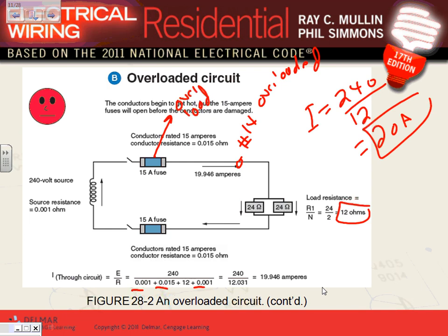That's an overload condition. What happened in an overload condition? This fuse will sit there in this situation probably for an hour, half an hour and a half, and it will open. So look at the amount of time that it takes to open. If you double it, probably you're talking about in hours from, I don't know, 0.4 of an hour all the way, say, to 1 hour. It might take 0.4 of an hour, 20 minutes or so, all the way to an hour, and it opens.